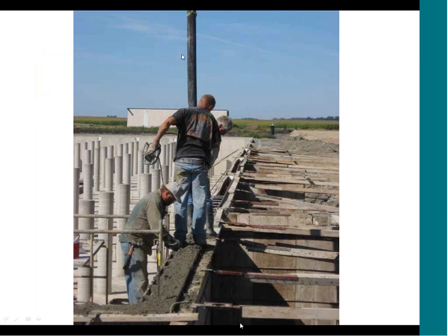Picture of the wall pour. You can see that the concrete is being pumped in and they're finishing as they go, and this guy looks like he is running the vibration to make sure that it's getting in there and it's a consistent cure, a consistent pour.